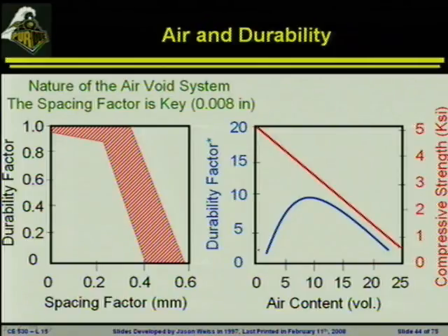One of the most important things is the spacing of these air bubbles. We talk about volume because it's the easiest to measure, but what we really would desire is a bunch of small bubbles that are really closely spaced so that they protect all the paste evenly. You can imagine this if we went to the real extreme. You've got a cubic yard of concrete and you've got 7% air pocket in the center of that concrete. Well, the edges of the concrete don't feel that at all. Right? What you want is something that's evenly distributed. And what they commonly look at is a term called the spacing factor, and the spacing factor really dictates how far apart the air bubbles are spaced.